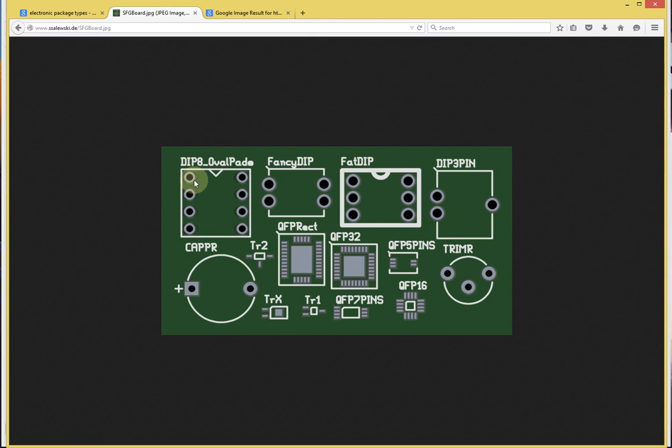That means that the pin, when the part sits on the board, will go through the board itself. So there are holes that are drilled as part of the board, usually plated through holes. The pin goes in on one side and comes out on the other. Collectively, the package itself on the PCB board is called a footprint.